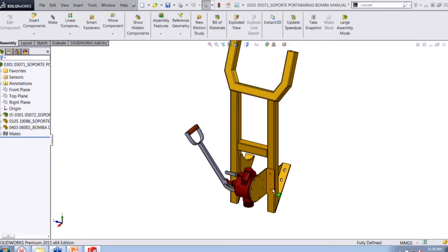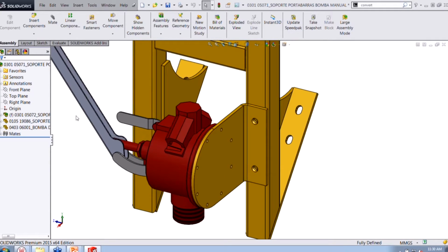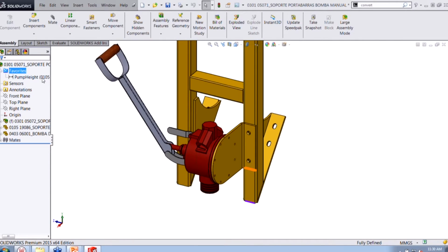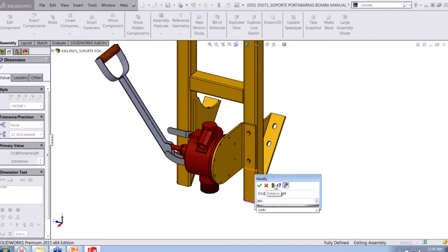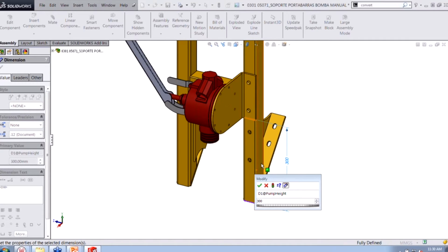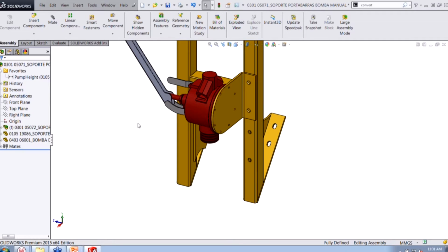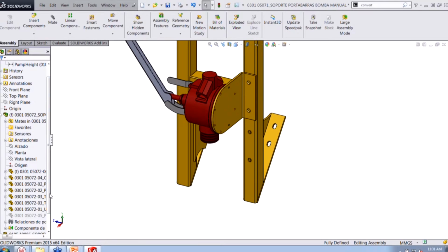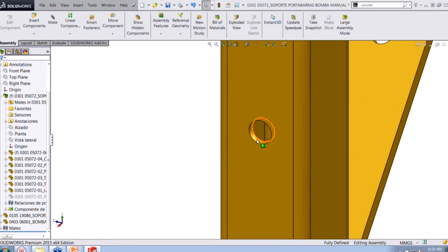So now this is what I'm going to be working with for my external references and my assembly features. I can see here that I have some holes that are lined up correctly, which is great. But if I modify this value, I'm going to find that the holes don't move, right? In that case, I want this to be driving the location of these holes, as well as the size. So one of the things I can do is first go ahead and delete these holes so I don't have them there already. There's no confusion.